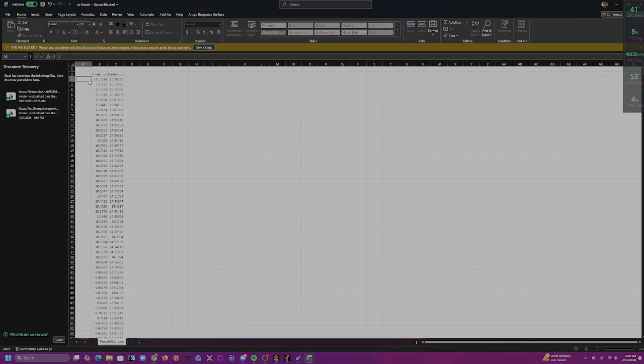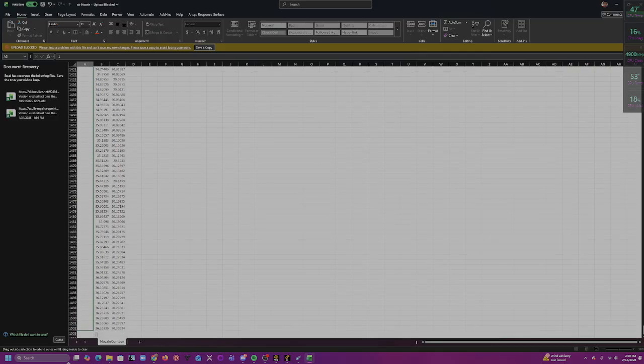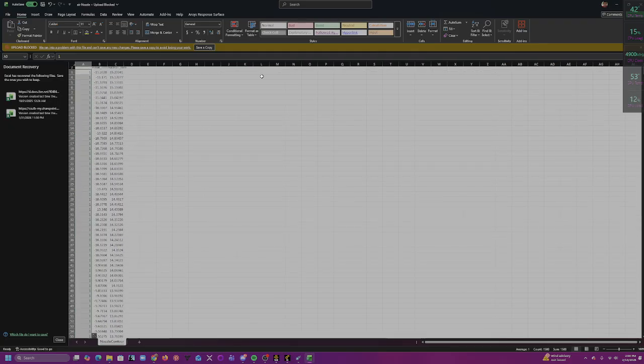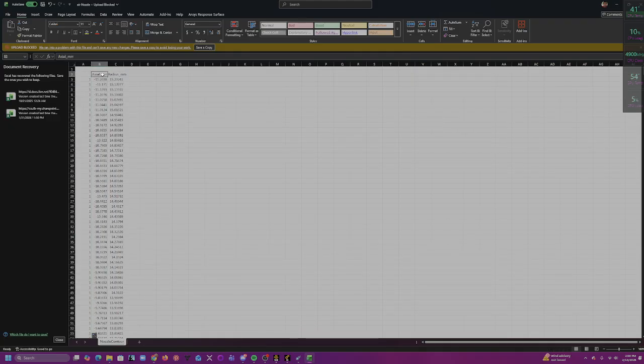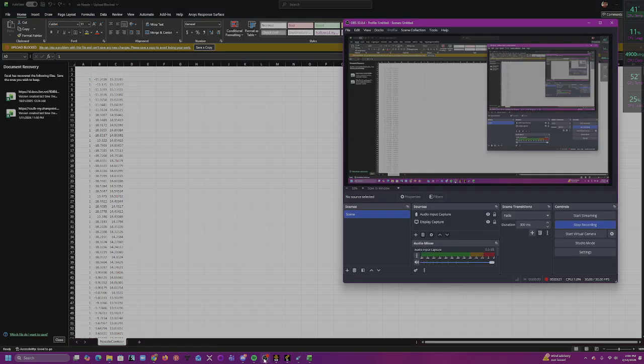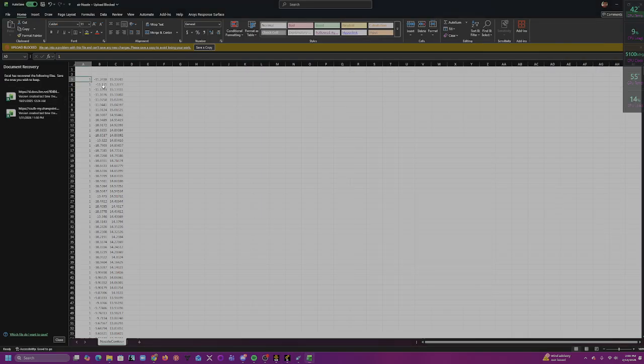Then we want to put the ones in the first column. So column 1. There you go. All right, now we can go ahead and erase these letters. And make sure this is recording real quick. Okay, we're good. Okay, so this is how your data points should look, that way we can easily import it inside SpaceClaim. So go ahead and press Control A, and it should be able to copy everything.